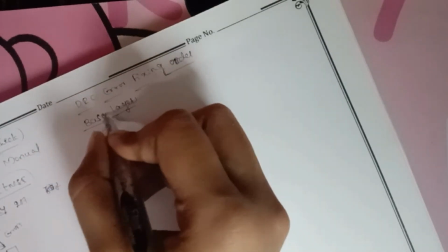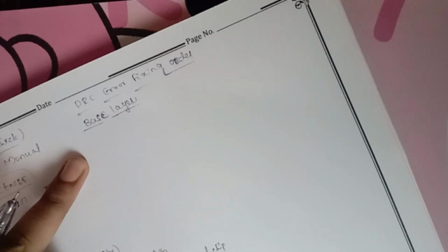After all, we have to remove all the things and manage everything another time, or we should do a new design. That's why we first go for the base layers. After placement, before routing, we will first ensure that base layers are clean. After that only we go for the metal connection and metal routing.